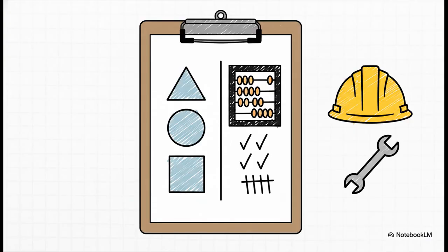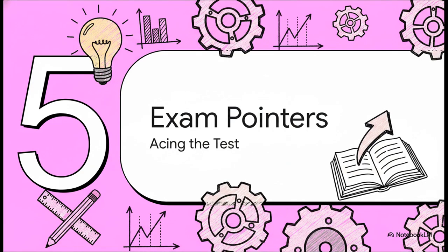Just to quickly clarify how this works, there are two primary parts to this standard that you definitely need to remember. IS 1962 Part 1 uses letter symbols to classify steel, whereas Part 2 uses numerals. Knowing this subtle difference between the letter-based and numeral-based designations ensures you will never get confused or misread a material spec sheet when you're out there on the shop floor. Let's move on and see how this builds into our final segment.